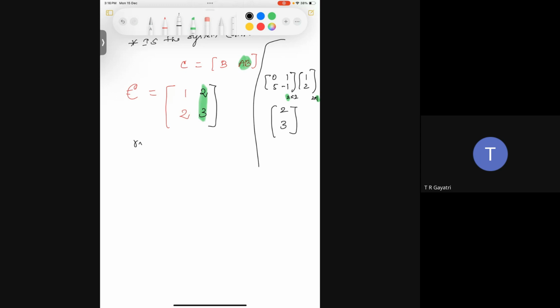So if I find the rank of this controllability matrix, and if the rank is equal to the order of my system, then the system is controllable. Otherwise, the system is not controllable. Right. How to find the rank of the C matrix? It's the determinant of C, right? The determinant also works. That is a shortened method. Otherwise, you have to find the row echelon form.